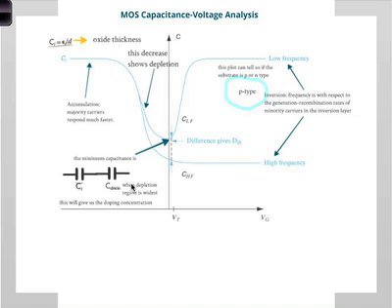The minimum capacitance, again, the capacitances are connected in series. The minimum capacitance, as I said before, is from Ci and Cd,min, and this is when the depletion region is maximum. Okay? The capacitance is minimum and the thickness is maximum, right? Remember, it goes as 1 over the thickness. And by knowing the minimum capacitance, and we know this number, because we just measured that, we can calculate that.